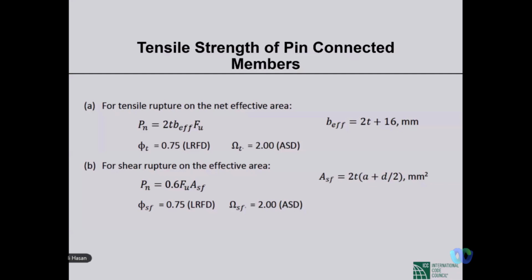Then we can calculate the yield stress, right? Because we pull a rod and find out the yield stress. But when there is shear and axial force, a three-dimensional arrangement of stresses, we cannot define yield stress like the way we define it in the stress-strain relationship of the one-dimensional case.